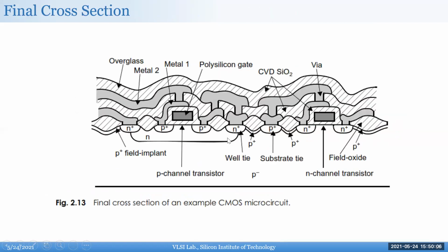Okay. And then once all the metallization is done, if you look at the cross section of, let's say, this P and N type device, this is what it looks like. It's kind of exaggerated, but it does look very unwieldy, especially the old process. Now they do what's called CMP. It's a polishing step, because if you have so much undulation, it's very hard to get very fine line features. So after every step, each material is grown thicker than it needs to be, and then they polish it. By polishing it, they bring that tolerance down a lot.